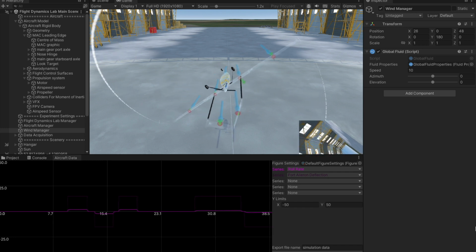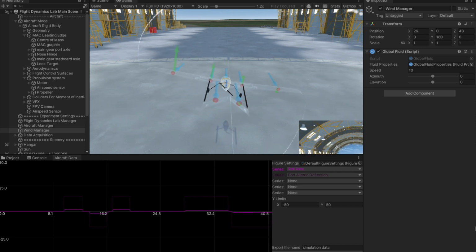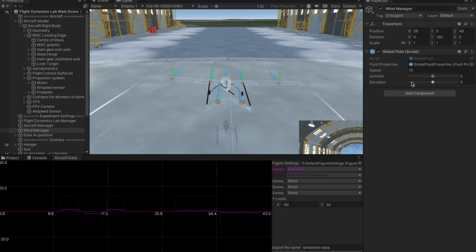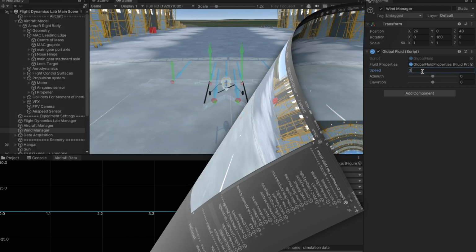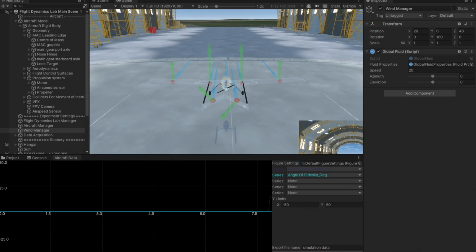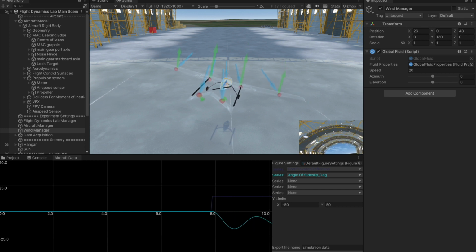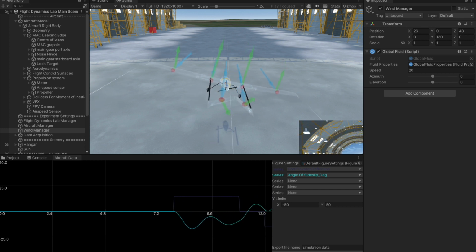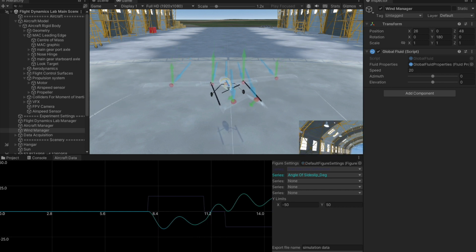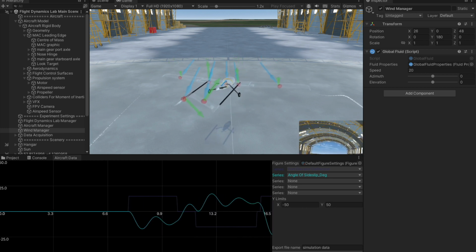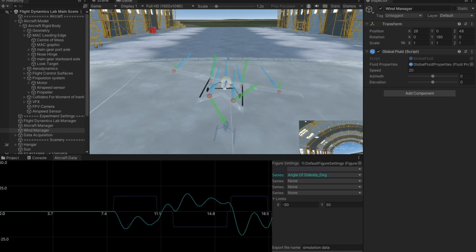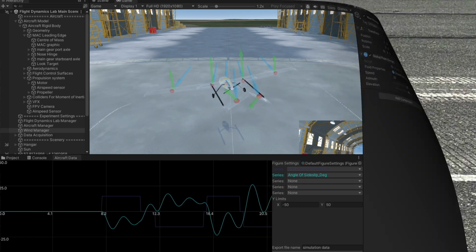However, prior to doing this, it is required to confirm that the rudder deflection provides an angle of sideslip that is of the appropriate sign. As a result of the analysis of the yaw response, it has been determined that the damping in yaw is significantly lower in comparison to the damping occurring in pitch. When compared to a new pitch trim state, this indicates that the aircraft needs more time to adjust to a new yaw trim state prior to reaching a stable position.